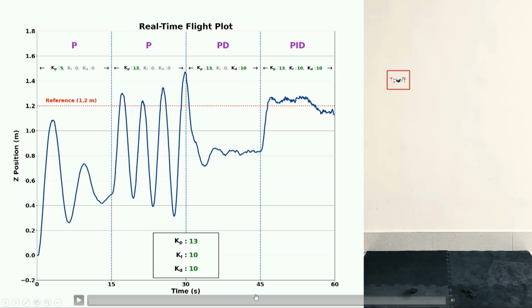From here you can understand that PID controller design is quite intuitive actually. You can look at the response and then design the PID controller. However, for all systems you might not be able to do it. If you are working on a system which might break down when run with a wrong PID, you cannot do it always. You have to be careful in those cases. You have to go for analytically finding the transfer functions or using the Ziegler-Nichols method that we have talked about.